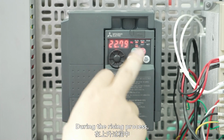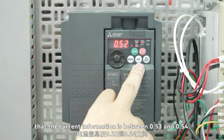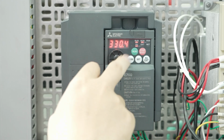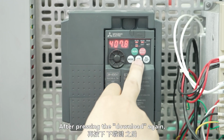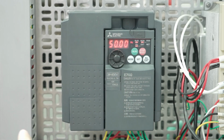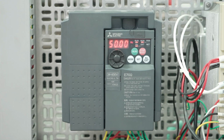During the rising process, press the set key, and you can see that the current information is between 0.53 and 0.54. Press it again, and you can see that the current rated voltage is also changing continuously. After pressing it again, it returns to the initial state. We can see that now the motor has reached a frequency of 50 Hz, which means that it is now running at the rated power.